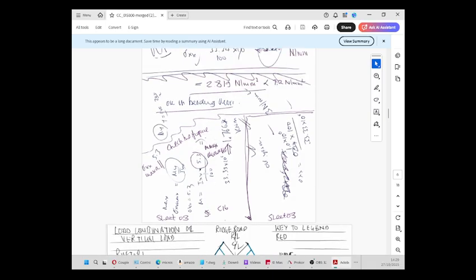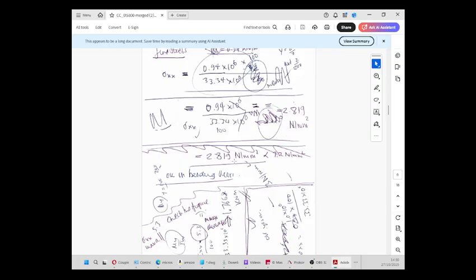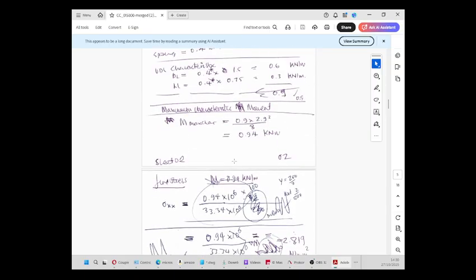Yeah, because the maximum, let's say it was C16, and sigma xx would be 5.3 max. Sigma xx max was My over Ix, so that would be 5.3, so M maximum applicable would be Ixx times 5.3 divided by 100, and so I reckon that would be 1.77 kilonewton metres maximum for a C16 joist, and we got 0.94, so we're okay.